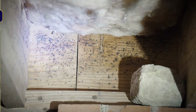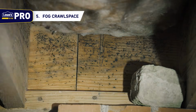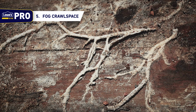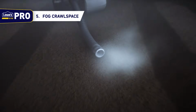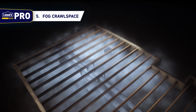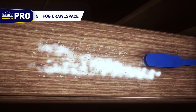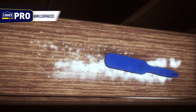Step 5. Fog crawlspace. Moist environments generate fungal growth, and over time, that fungus can lead to mold growth. Destroying the fungus before that happens is crucial. To kill off the fungus, you'll need to fog the crawlspace. This is best done with a cold fogger machine filled with fungicide. Be sure to follow specific manufacturer's instructions. If there is any remaining fungus, remove it using a nylon brush and soap and water or a chemical cleaner.